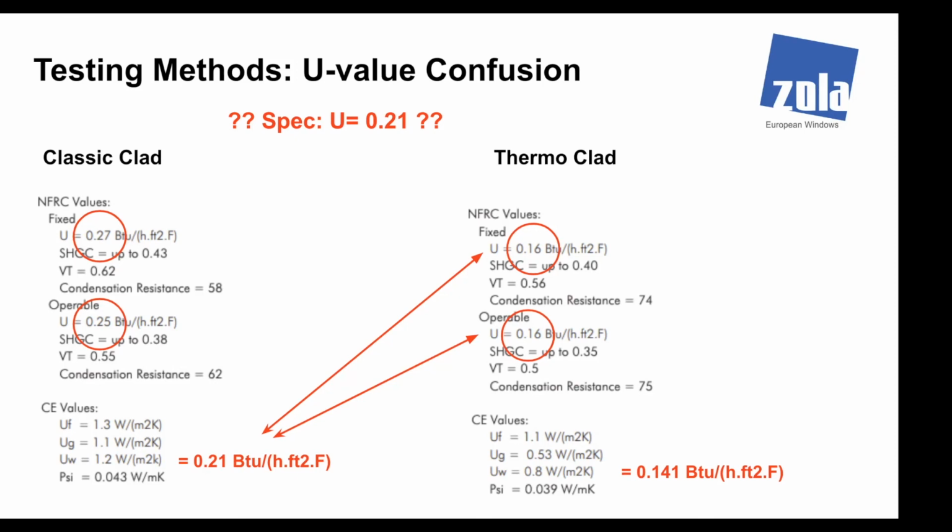Thanks, Caleb. So Dennis asks, will an affixed window insulator's attachments be evaluated the same as new windows? Well, the attachment to the actual building, the installation value, is a passive house assessment. We of course provide metal clips, but how you use them, how you protect them, how you stop the thermal transfer and the install detail, that's over in the passive house realm. We certainly could help with it, but we don't draw that. And every project's a little bit different.